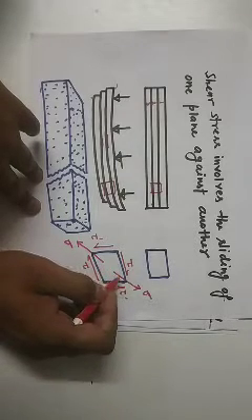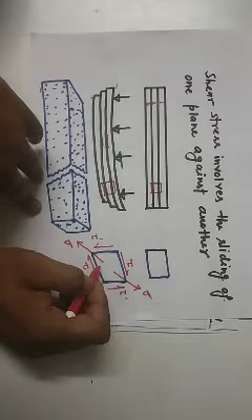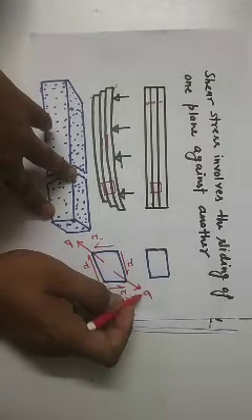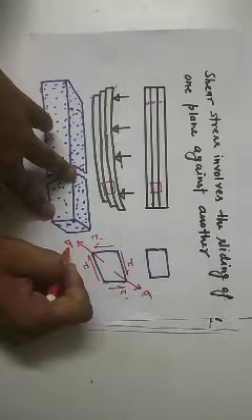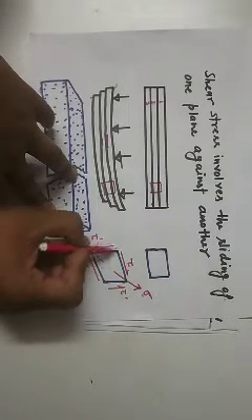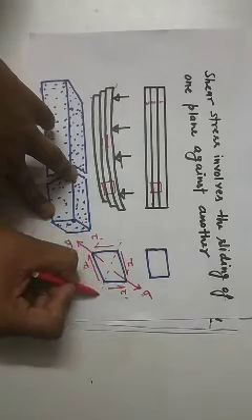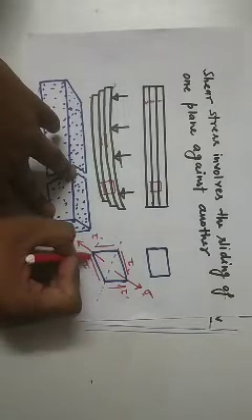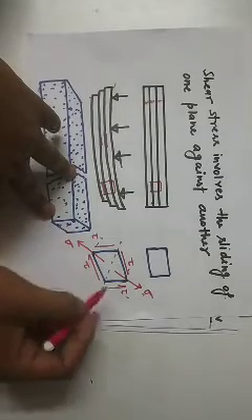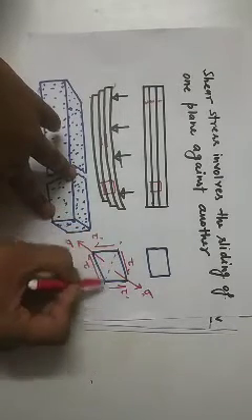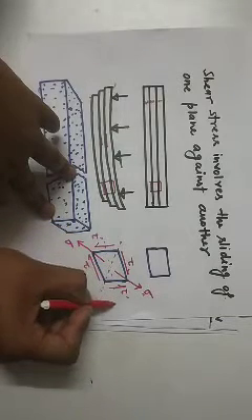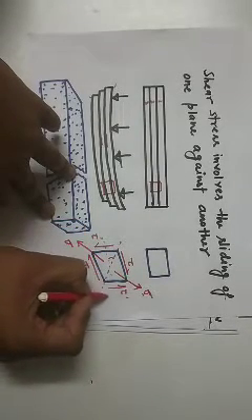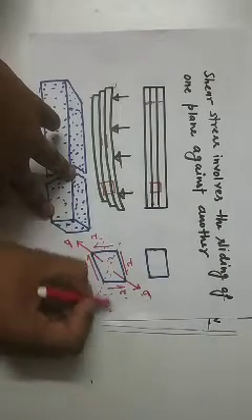The resultant of these four stresses will create a pull effect on the segment. These stresses put the whole section under tension along the diagonal of the segment. So we can say that this segment will shear off, tear off, break off along this cross section, at 45 degrees from the axis of the segment.